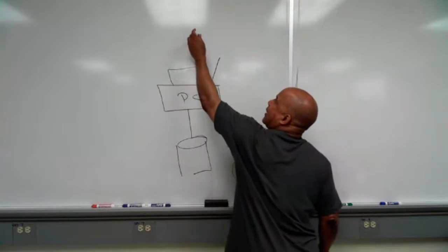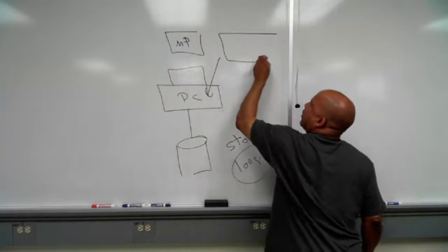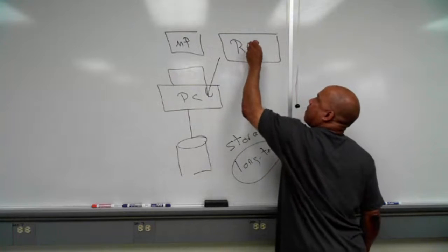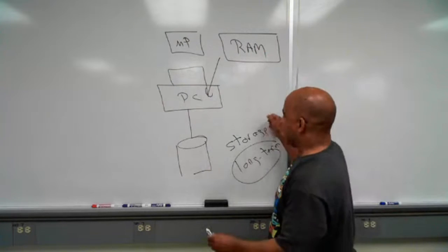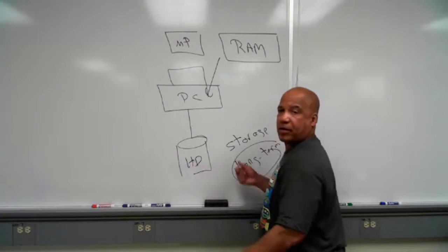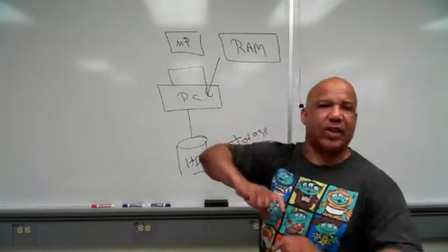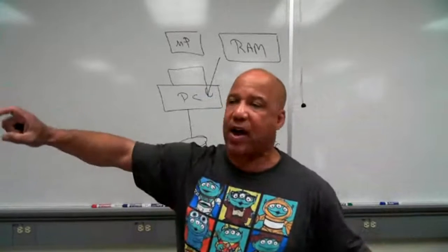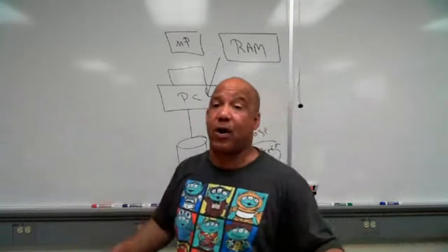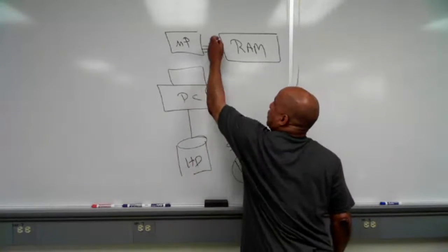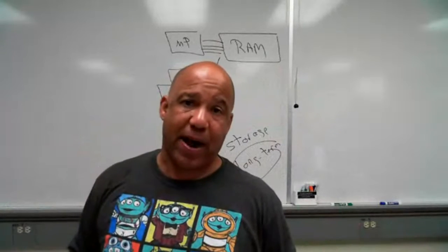Inside of that, typically you have your microprocessor in there. And then you have this big chunk of memory here, and it's always RAM. So really, storage and memory are two different things. When you're talking storage, you're talking your hard drive or your thumb drive or something like that. When you're talking memory, you're talking an actual chip, separate from storage, separate from your hard drive, usually placed in close proximity to the microprocessor. And when we talked about data transfer, typically this data transfer is parallel data transfer because you've got to be able to read to and write from the memory really, really fast if you're the microprocessor.